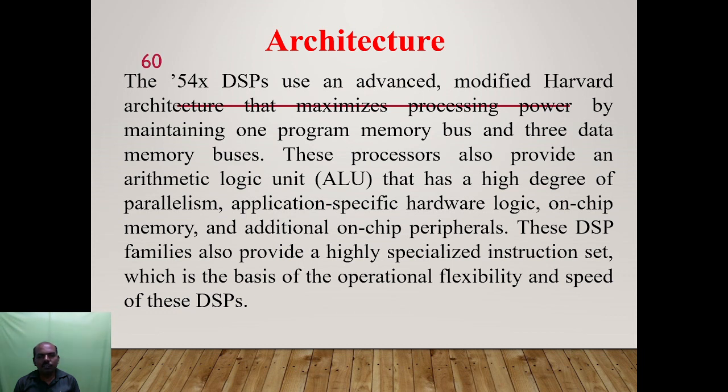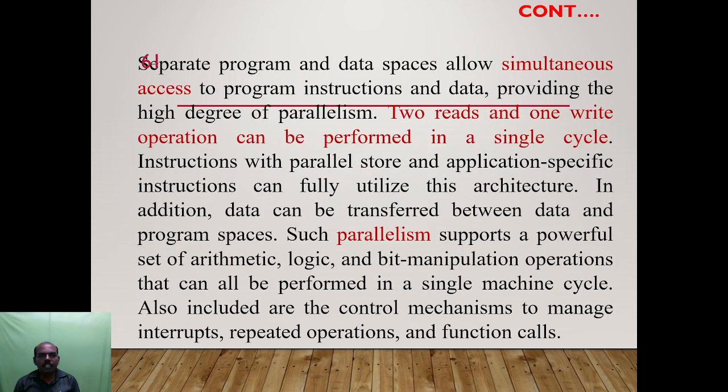These DSP families also provide a highly specialized instruction set, which is the basis of the operational flexibility of this DSP. Separate program and data spaces allow simultaneous access to program instruction and data. Two read and one write operation can be performed in a single cycle.